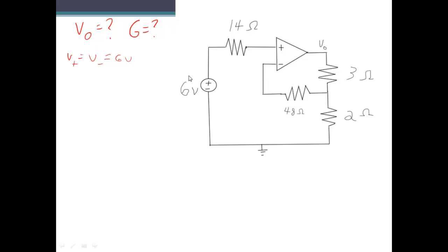So the next thing we want to do is find out what V out is. Since we just said that the voltage across this resistor is 0, since there's no current coming through it and it's not contributing anything to the circuit, this right over here just starts to look like our normal voltage divider rule. And so we can use that equation to solve for V out.